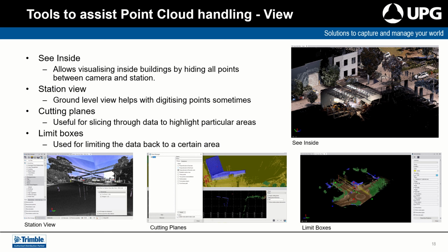The cutting plane can also have a position that's the default position, so that's the 0 value for the cutting plane. However, there is a slider along the bottom of the view that allows you to slide up and down the view to the axis that you are referencing to see different parts at that cutting plane. On the right-hand side, down the bottom, next to the left and right arrows, there's a little icon that allows you to also manually insert a subplane that you can reference back to later.